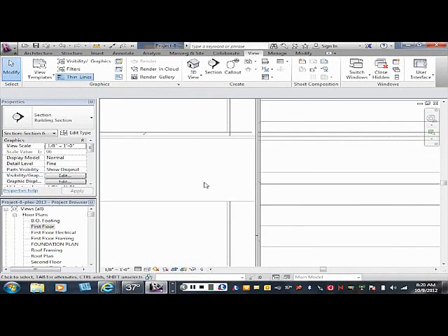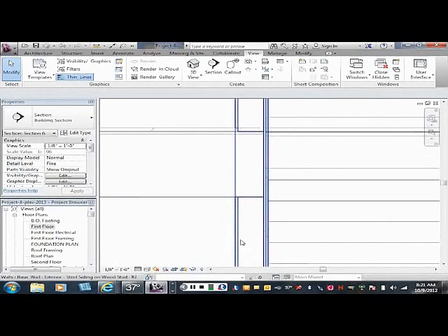In this case here, now we want to put in some detail to represent this. So in reality, when we put in our exterior walls, we put in a wall that was, what, 17 foot 9 inches tall, but in fact it's two walls. It's a wall that comes up to the floor joist and stops, and then a new wall starts above the floor joist. So that's why this floor truss goes into the wall. Let's add a detail there of those top plates and bottom plates and so forth.